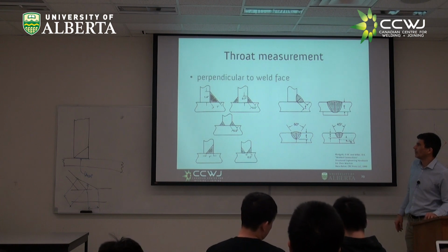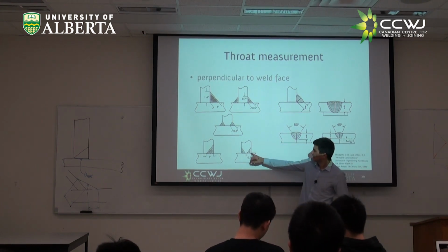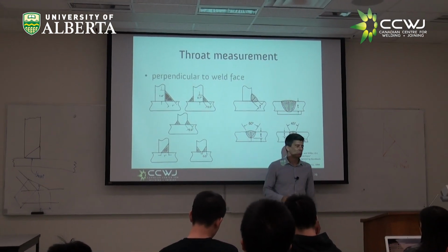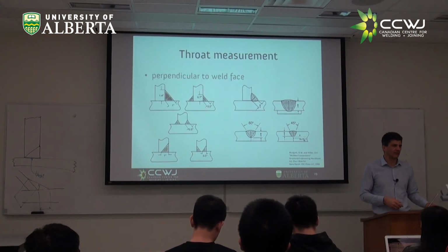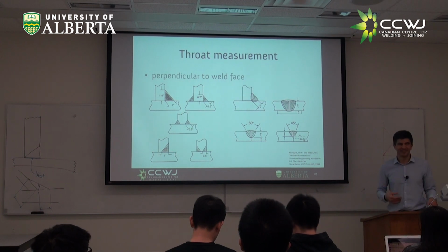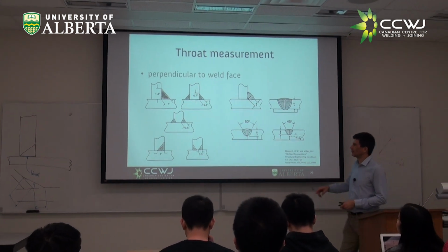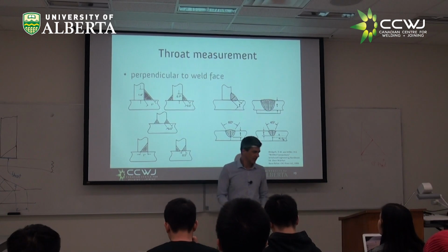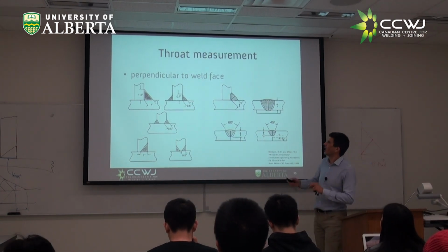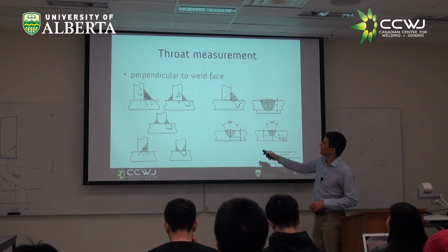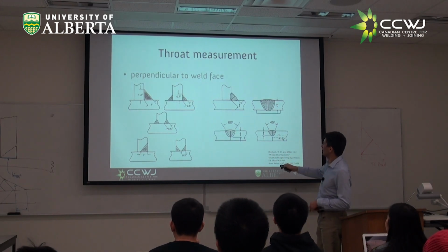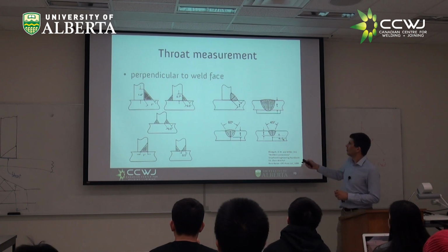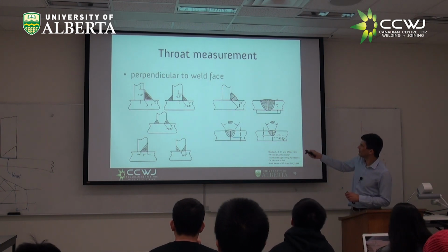The throat. Now, you would argue that if you went from here to there, you'd calculate a smaller throat, right? They don't. We go perpendicular to the face. Here, here, here, perpendicular to the face. Here we have, for partial penetration welds, how you do the throat.